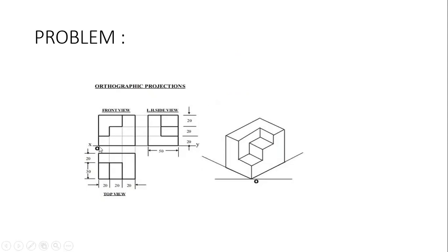So what is the scale dimension here? This line height is 20 mm. From O, we have to draw a vertical line of 20 mm and a horizontal line of another 20 mm. Then we repeat the same pattern by constructing a vertical line, a horizontal line, and again another vertical line. All the dimensions are equally 20 by 20, both vertical and horizontal lines.